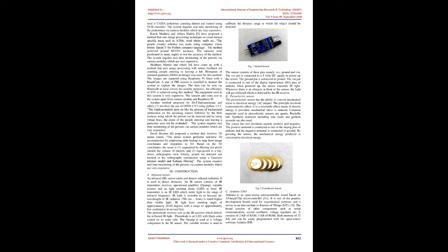The algorithm devised for this method is implemented using ARM Cortex-M4 and Raspberry Pi 2 modules. Two IR-UWB sensors with antennas are fixed to count the number of people. Though the system can detect multiple people at a time, it is not cost efficient. The sensors are highly expensive in the market.